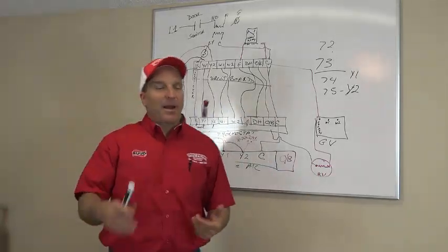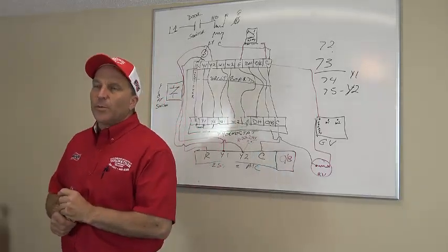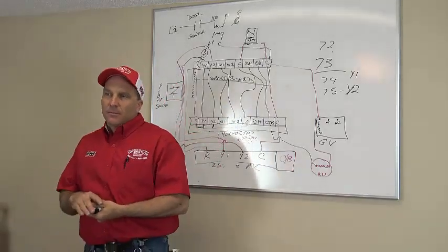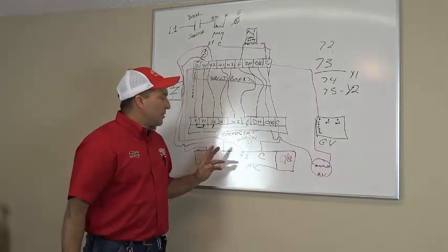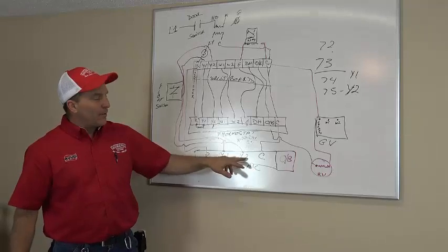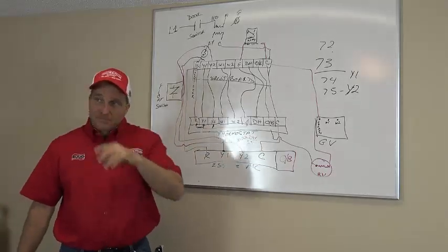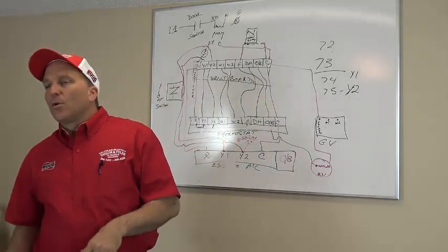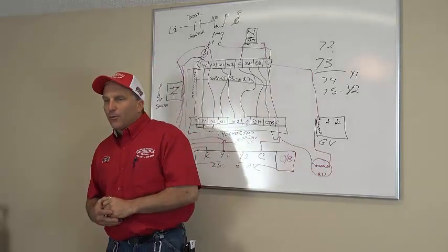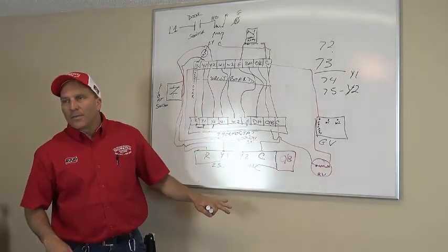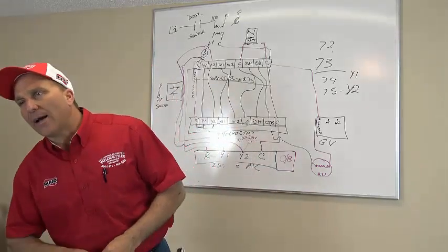Am I getting my full capacity? No. Nope. How would you know that? What would you be able to tell? You're not getting anything to Y2. You are getting to Y2 because the Y2 is on your 24 volts. But Y2 going through your circuit board energizes the solenoid valve on your compressor. How would you know that Y2 is not getting energized so that you're getting full capacity? Your voltage is getting to your circuit board. It's just your compressor's not kicking in second stage. How do you know that?